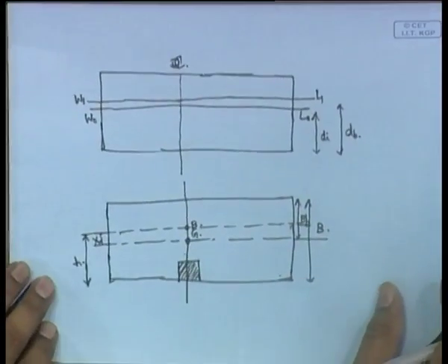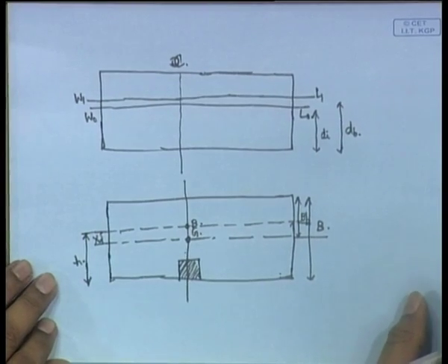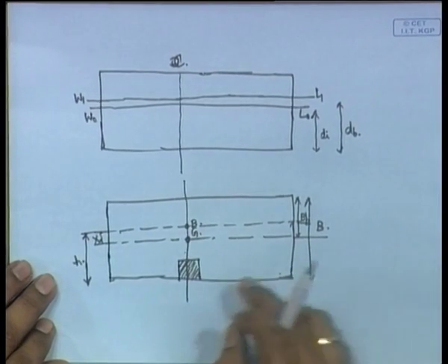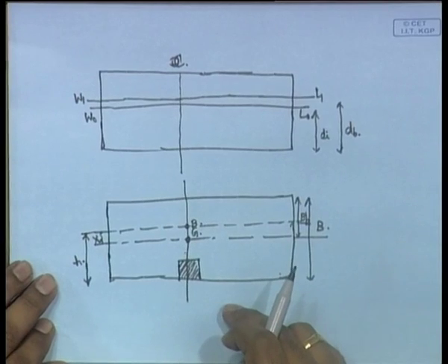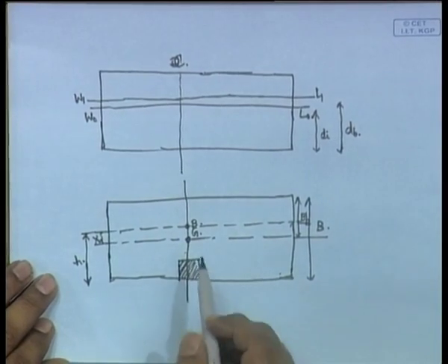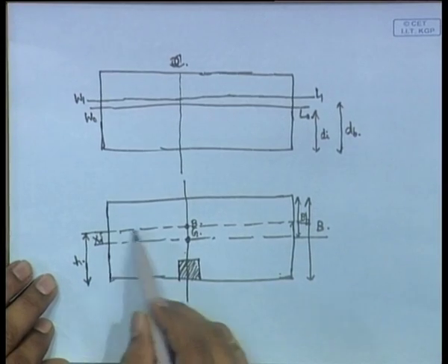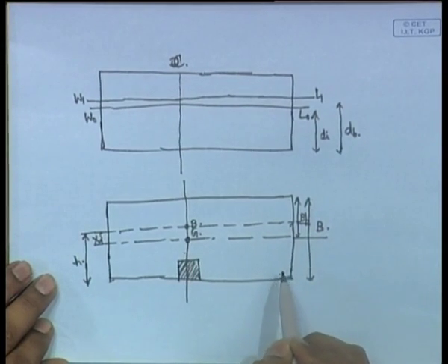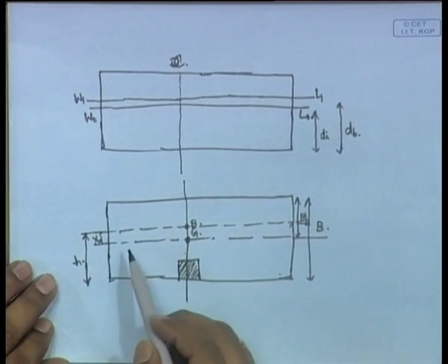Now, in this case, since it is a box shaped vessel, we can just calculate area, you do not need to calculate volume, everything is at the same draft dB. So, instead of taking the volume we take the area, because draft is the same in all cases, it is just constant.